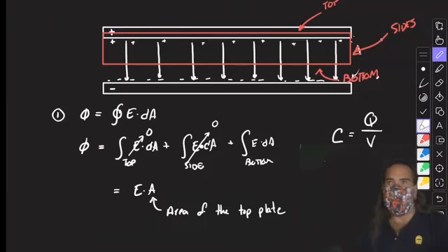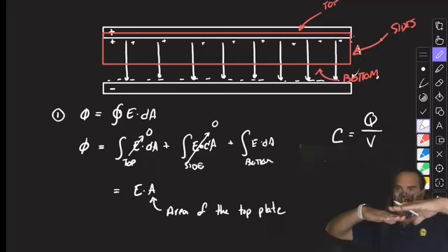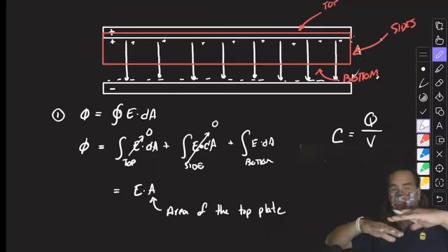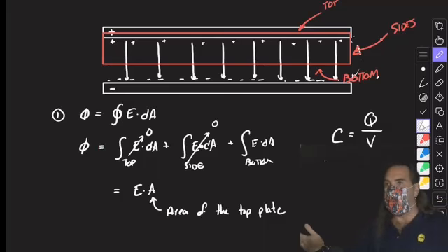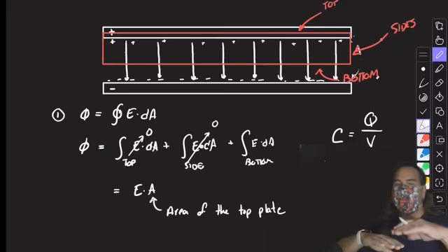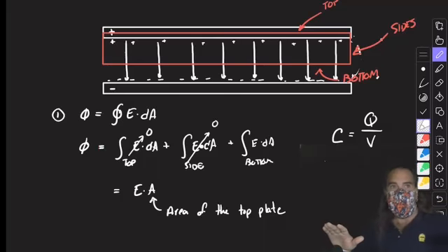Capacitance that we're calculating here will only include the parts of the electrical plates that overlap each other, and will not include portions of the plates that don't overlap. So if you have two plates and they are not overlapping, only the parts that overlap create capacitance, because our calculation is based on that. Now, there might be more capacity there than we know about, but our calculation is only dealing with the part that overlaps. None of that matters.